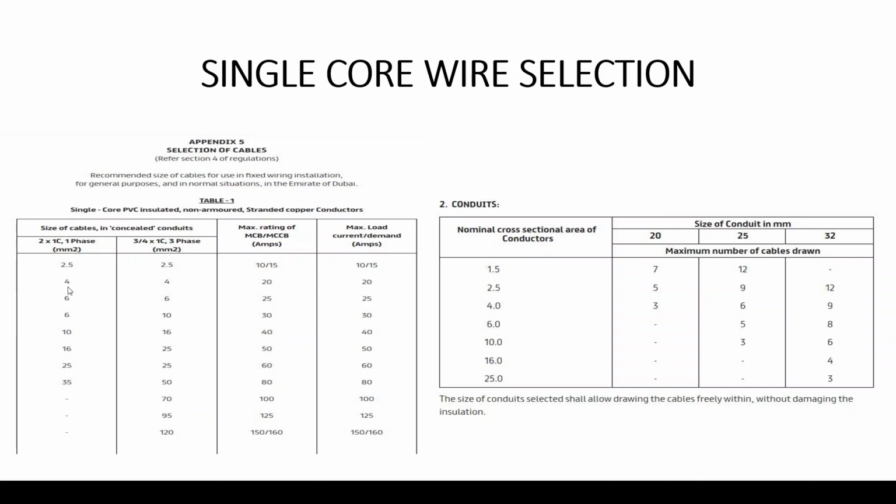You look through the table here and you would use 4 mm. Again, if it's a single phase, then you would use 3 number 4 mm. If it's a 3-phase circuit, how many would you use? You would use 5, since you have the 3 phases RYB, and you have the neutral, which is again 4 mm, and you have the earth, which is again 4 mm.